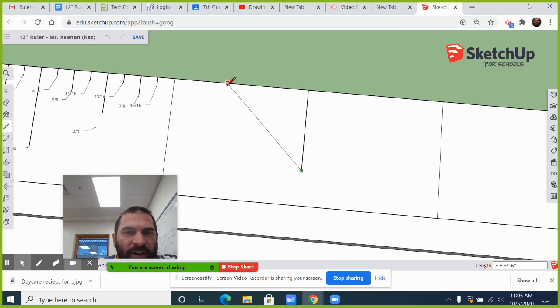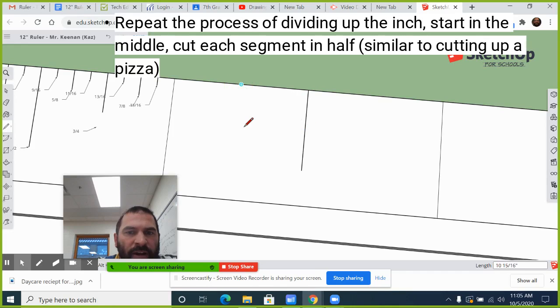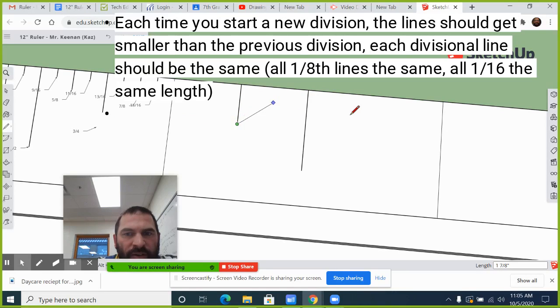You could also do something like this to make sure it's the same length. Whoops, it moved. Do it again. Go slow. The red dots should line up and everything should snap in for you nice and neat, just like that. Hit escape. I come here, do the midpoint of this one and come back this way, just like this. Then I'm going to come here, midpoint, come down, so it should line up with this one, just like that. Hit escape. Notice that these are all spaced out perfectly, and they're all perfectly the exact same length. Then we're going to hit escape again.